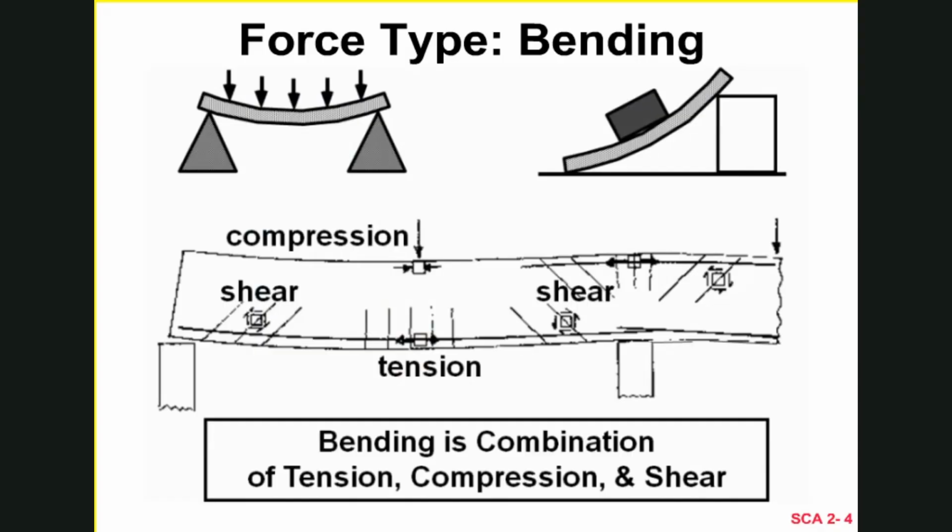And what we do then is we observe or monitor those cracks, and if those cracks don't change, we can make a judgment that the structure is still fairly viable. The ways that we monitor the cracks can be as simple as painting them with red paint, and then if one can see white lines through the red paint, eventually one knows that the cracks have opened a little bit. So that information is helpful to us in making judgments during an incident.